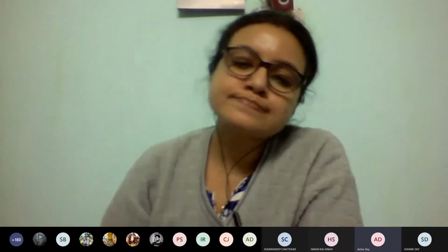Regarding the laboratory report, we should tell them to write. I think Rajdeep sir will send you the mail regarding report writing. Whatever table we have done for this experiment, you do this, and you also do the graph for Thevenin's theorem. Extrapolate this to get VThevenin and ISC graphically, and also find out the RThevenin graphically.